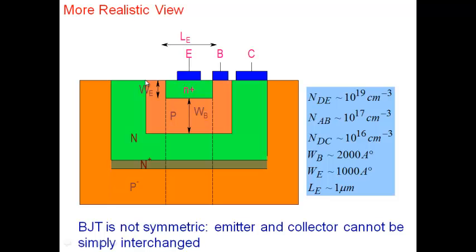So silicon dioxide acts as a mask. So when you're diffusing the impurity, N-type impurity will not diffuse here because that region is protected, while it would diffuse here. And so that's how you do selective doping. Yes, you're doing selective doping in some region N plus and some region P and some region N plus and all that. Anyway, processing is an interesting area. How do we make all of these things? That's something that you'll get an opportunity to take a course which will discuss all that in more detail.